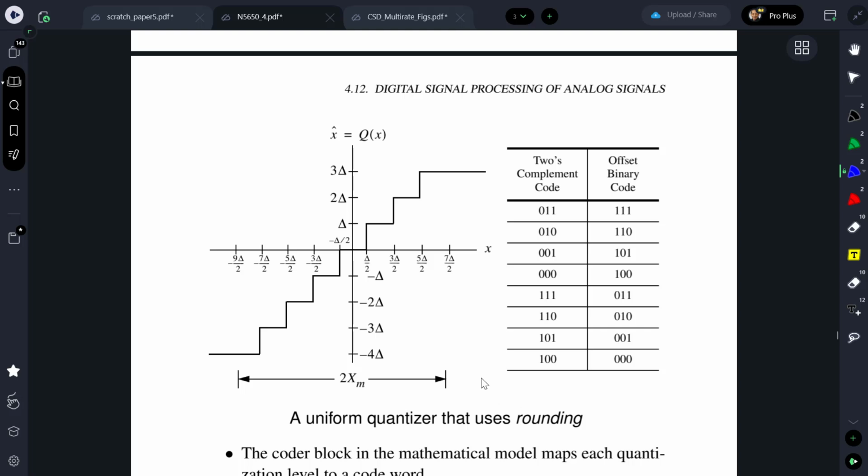except because we have a power of 2, this stair step corresponds to this one, and this one doesn't exist in the top half, and that's the very nature of signed arithmetic, and 2's complement reflects that fact in terms of the codes that you get moving from top to bottom. So everything that I say really refers to what's done today, and that's 2's complement.